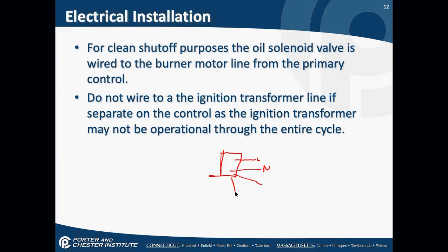And then it will have 3 wires coming out of it. Okay, it has an orange wire. The orange wire always goes to the burner. It might have a blue wire and a purple wire. Okay, purple wire, you have to look at the diagrams on the box, but this could go to the solenoid. Okay, the blue wire would go to the ignition. Sometimes they're exchanged. Always look at the labeling. Okay. As long as you have all of these wires, you know exactly where things go.